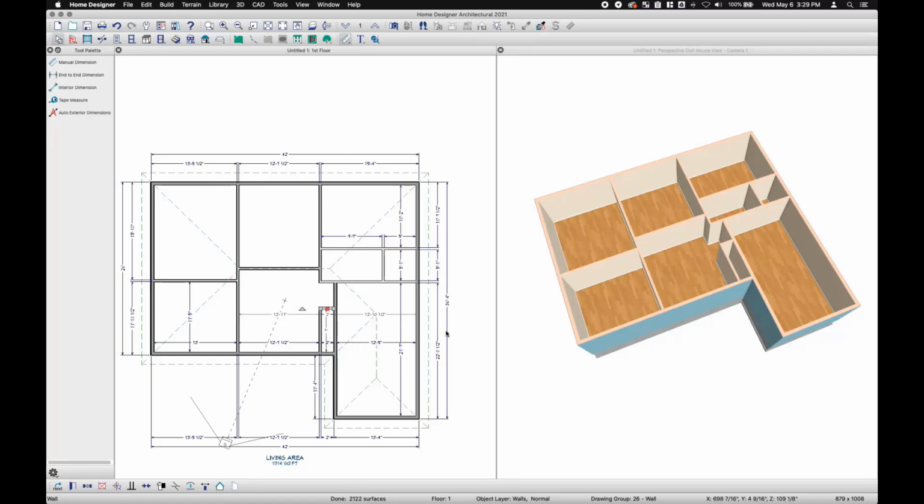The last thing to do is open the back wall of the entry area. I want to keep the two rooms defined as two separate rooms, a dining and an entry area, but I want to have it appear to be open between the two of them. To do this, I'm going to select this wall, then I'm going to click on the Make Invisible button down on the Edit toolbar. This will make it so that the wall is still there, dividing the two rooms, but the wall does not show up in 3D. You can see this in my 3D view.